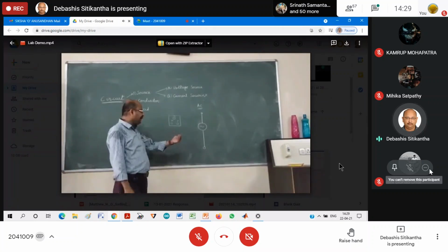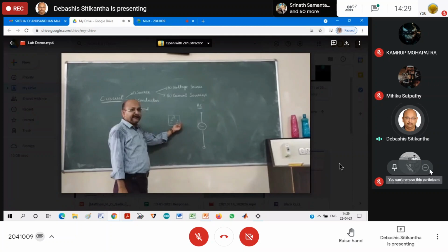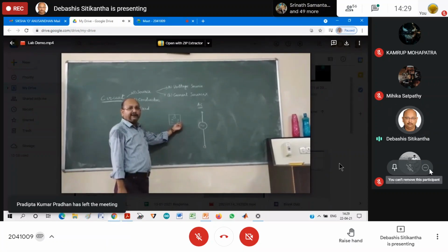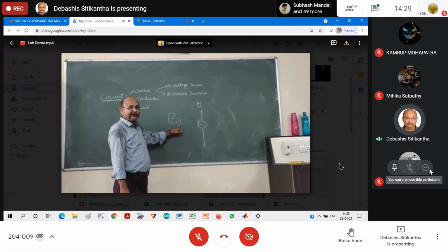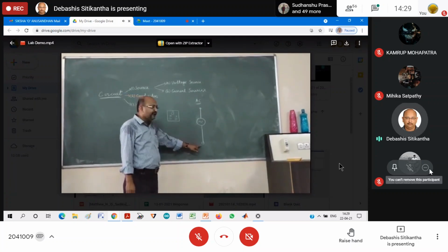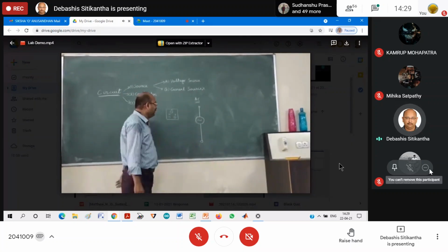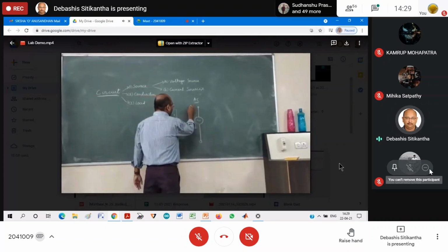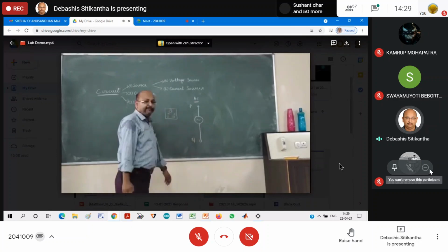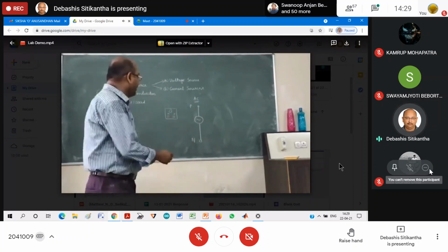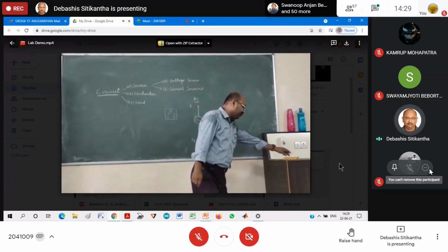you will take the Neon tester and put it inside this hole, and you will see that the Neon tester is glowing. So that particular terminal which is glowing when using this tester is known as your phase terminal, and the other one is known as your neutral terminal. So we will get this one as phase and this one as neutral. Okay. So this is how we represent an AC voltage source.